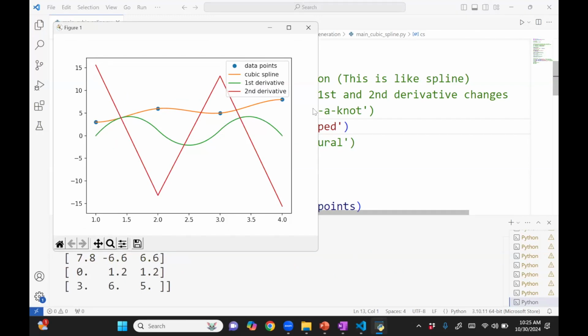Okay, so here is what you get. The orange clearly passes through all the data points. Velocity starts at 0, ends at 0, nice thing. But look at the acceleration. It jumps from 0 to 15. Terrible for the motors. Goes negative, positive, negative. Eventually, it comes to a rest.